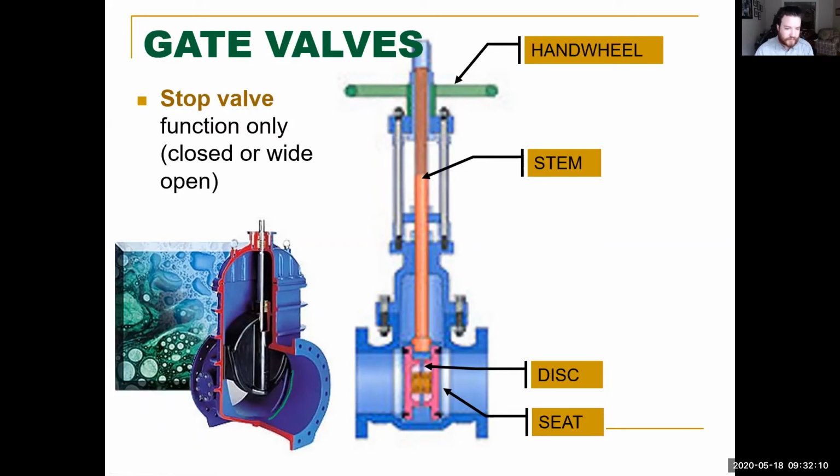All right. Now, the big thing about the seat is that it's actually going to be indented a little bit. You can kind of see it in the picture on this side, and then you can see it over here on this picture. Both of these are indented so that the disc can push all the way down into it. And once it's in, that gives your metal-to-metal sealing.